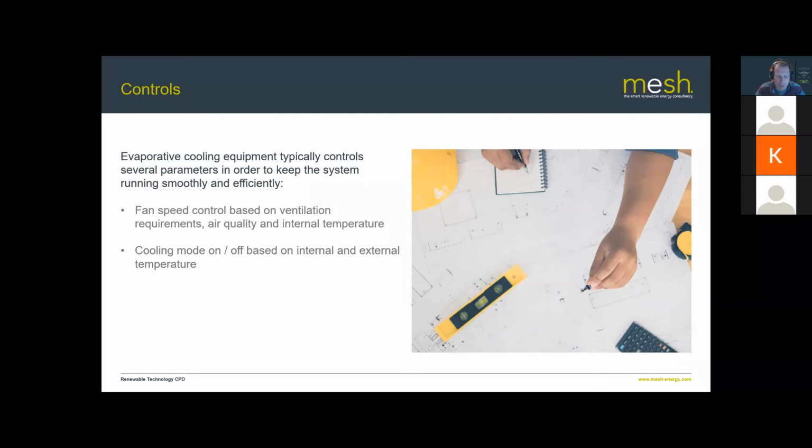So this was a process that was used for aerospace manufacturing, and what they were doing was they were effectively taking a very, very fine dust of copper and spraying it onto the leading edge of wings for aircraft, so that they could be used as a sort of defrosting element. So you pass electricity through that film of metal that was left, and it would then heat the metal up and defrost the wings.